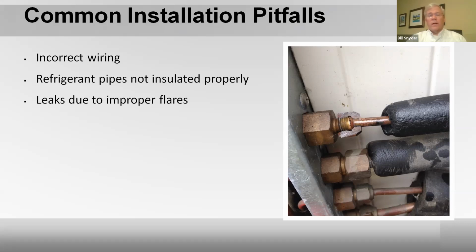They may work fine for low pressure air systems, or maybe even an old oil burner or something like that. But when you're talking of R410, you need to have a very, very good quality flare. If you put a good flare on there and you torque it per specs, you will not have a leak like this. So that's a problem.